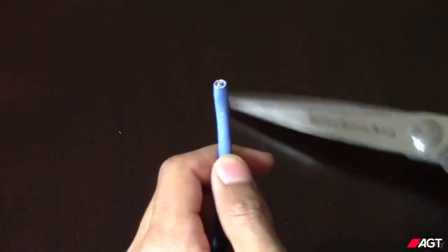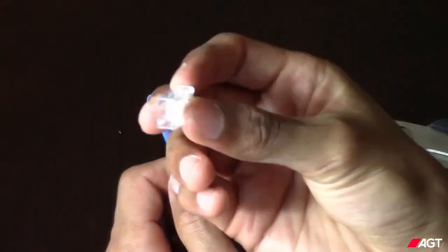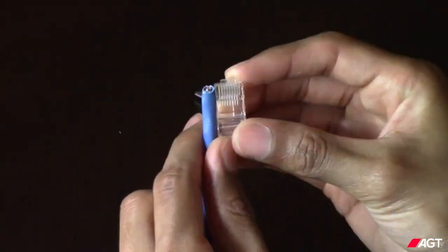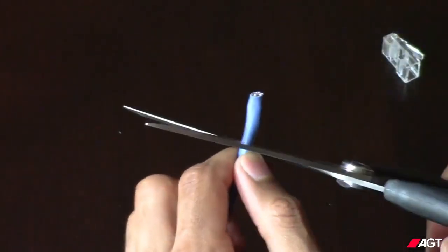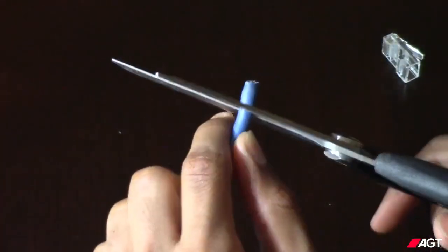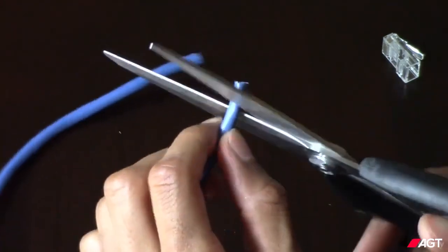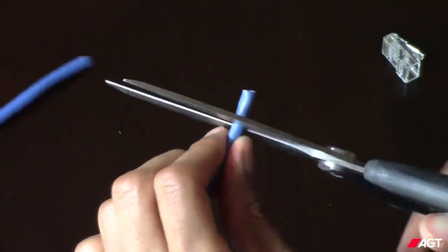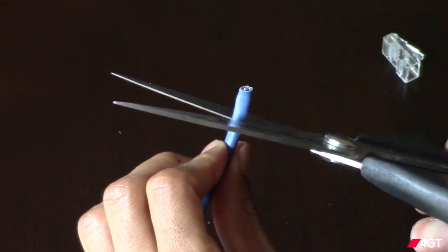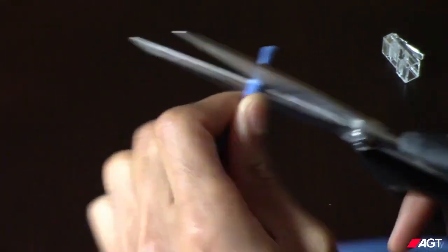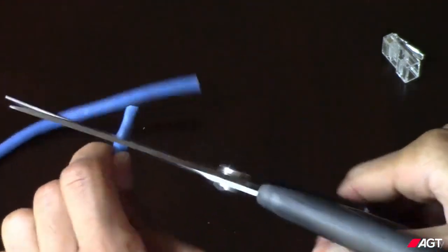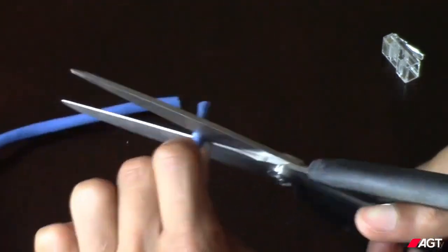Now, I've seen some beginners measure out where they're going to cut by using an RJ45 to measure where they'd cut the sheath, then simply strip the wire and add the connector. You wouldn't do that professionally because you could ultimately end up with some damaged wire if you use that part of the cable. So I'm going to show you how to do this the right way. I'll start off by cutting off some of the shielding.